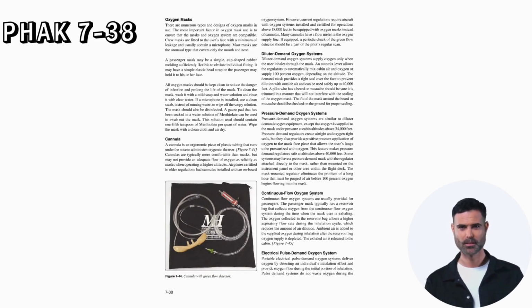Oxygen masks. There are numerous types and designs of oxygen masks in use. The most important factor in oxygen mask use is to ensure that the masks and oxygen system are compatible. Crew masks are fitted to the user's face with a minimum of leakage and usually contain a microphone. Most masks are the oronasal type that covers only the mouth and nose. A passenger mask may be a simple, cup-shaped rubber molding sufficiently flexible to obviate individual fitting. It may have a simple elastic head strap, or the passenger may hold it to his or her face.